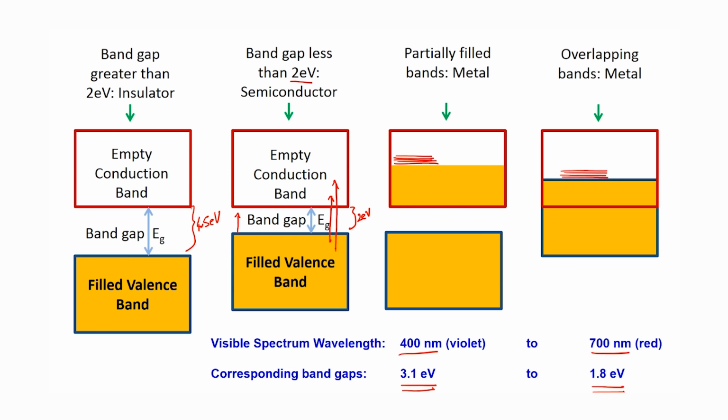With a semiconductor there are ways in which you can now pull off the electron and then take it to an external circuit. So, as we look at this photovoltaic approach to dealing with solar radiation through our next few classes, that is the idea that we will look at. How is it that we can use semiconductors to create the situation where you have these electrons that can be pulled off into the external circuit and then used as a power source which can then run something usefully. So, for that we need to understand all this idea of how these bands come about, what is happening, is there some more detail in this band structure that we have not fully captured, are various materials with the same band gap exactly the same in terms of how they handle the solar radiation.